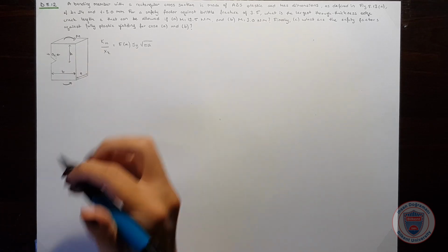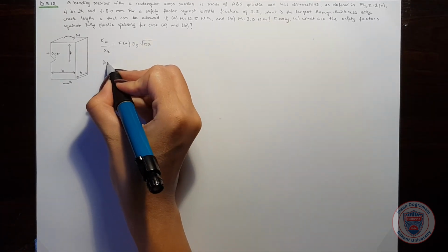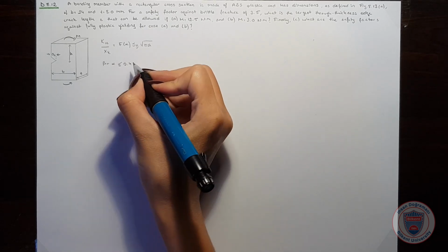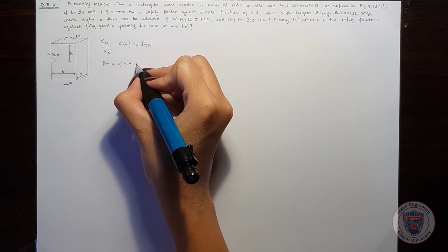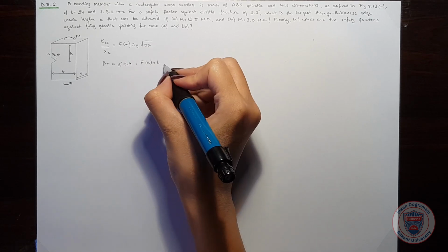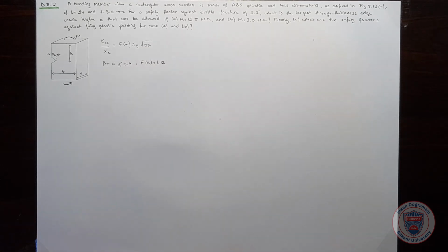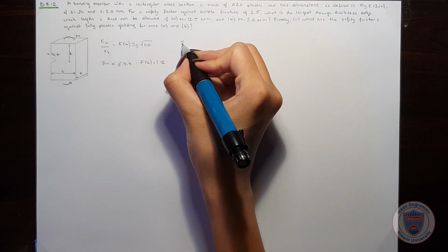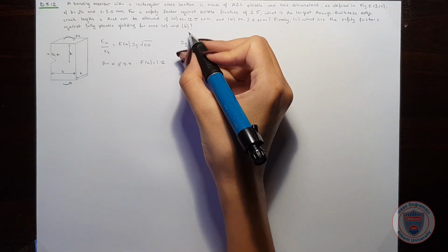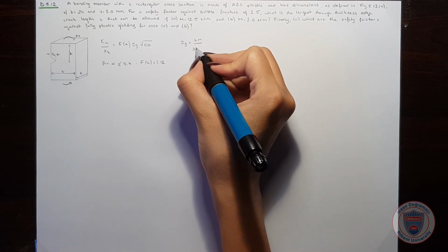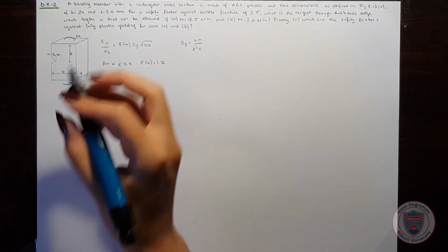And for this shape, for alpha smaller than or equal to 0.4, we can use the form factor as 1.12. We also know that S gross will be equal to 6M over b squared times d.